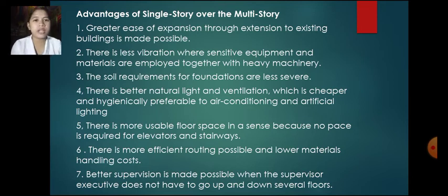First is greater ease of expansion through extension of existing buildings. Second, there is less vibration where sensitive equipment and materials are employed together with heavy machinery. Third, the soil requirements for foundation are less severe.